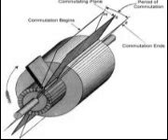The poles are usually laminated to reduce eddy current losses, as in figure 9-9, a typical aircraft generator, and serve the same purpose as the iron core of an electromagnet, that is, they concentrate the lines of force produced by the field coils. The entire frame, including field poles, is made from high-quality magnetic iron or sheet steel.